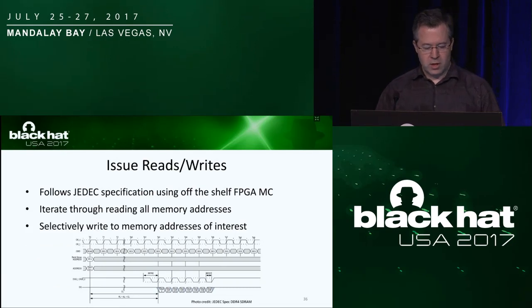So finally, we want to issue reads and writes. This is where we actually can read the data. And here we're not doing anything tricky. We're just following the JEDEC specification for how reads and writes are conducted. If you've seen the spec, it's many bubbles in a state diagram with all sorts of conditionals. So we didn't put that on here, but essentially the reads and writes will be used to scan through all of the memory. We can essentially copy all the memory out at that location.